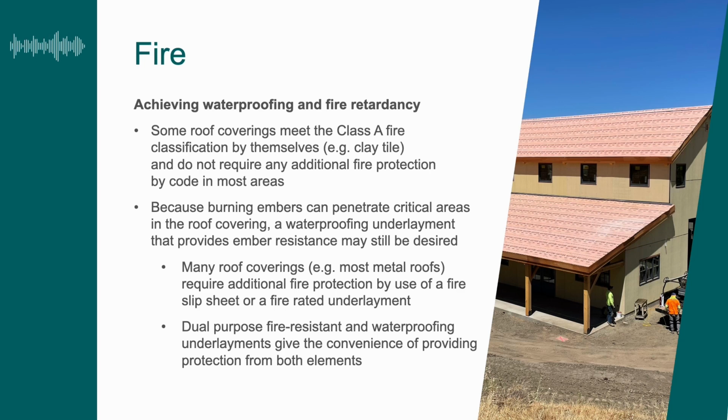If you put a full self-adhesive underlayment that's manufactured specifically to enhance these two characteristics, you put the roof covering on, and then you really don't have any worries in the future about how the system's going to perform. You can lose part or all of your roof covering, and your customer's roof, your client's roof, is still protected from water intrusion. Okay, I'm going to pass this off to Marco, and he's going to bring the last portion of this home.